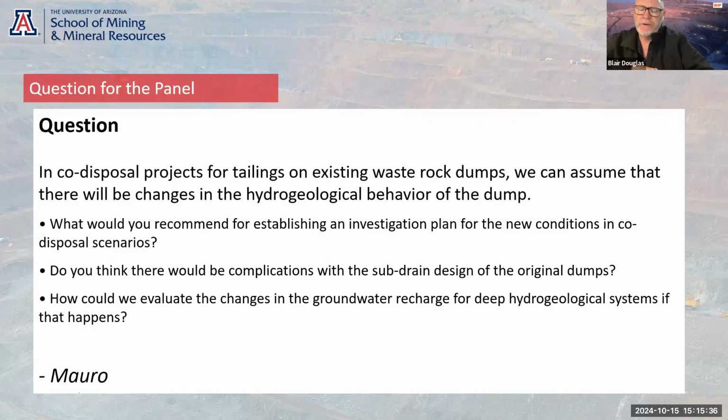Just to add to that, Jeff, I'm not sure what the subdrain design is, but if you've got fairly wet tailings, let's say somewhere like 60%, and they're free draining, you may find that if the drain's not designed adequately, you'll block it pretty quick, because of the differential in grain size between the waste dump and the tailings. So if it's a low solids tailings, you definitely need to be careful with it.